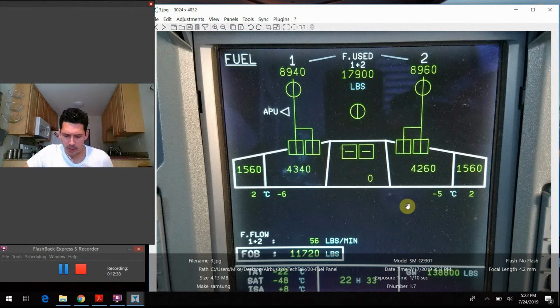So the other one to talk about, interesting also, they're not actually depicted anywhere on this status display here, is that we actually have these suction valves in the wing tanks only that allow for fuel to gravity feed to the engines. If for some reason you had no pressure, no way of getting fuel through the electric pumps anyways, these suction valves will automatically open up if it detects a loss of fuel pumping pressure, and the plane will just keep on flying like normal. It's a pretty basic system that Mother Nature helps us to continue an uninterrupted flow of fuel out to the engines there.